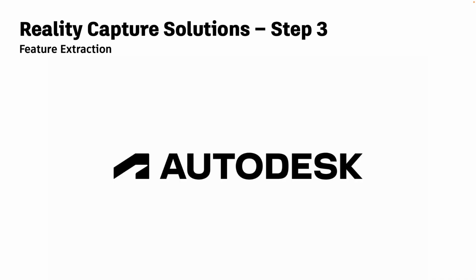Three steps. Step number 1, create the project, click the import button, bring in your point cloud data, set up the coordinate systems, and press OK. It creates it and it's right there. Step number 2 is publish to ACC or BIM 360.